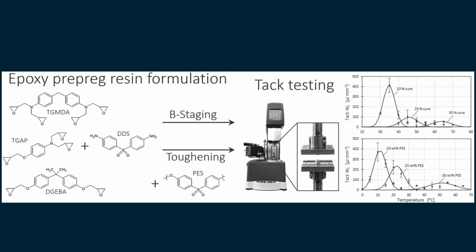Epoxy formulations containing aromatic amines can undergo B staging, in which partial reaction produces a glassy but still fusible intermediate material. These B-staged materials remain stable for extended periods and can later be fully cured by heating. This property enables the production of solid adhesive forms such as powders, films, or dry coatings that function as one-component adhesives with long shelf life. Common aromatic amine curing agents include meta-phenylenediamine, MPDA, methylene dianiline, MDA, and eutectic mixtures derived from these compounds.